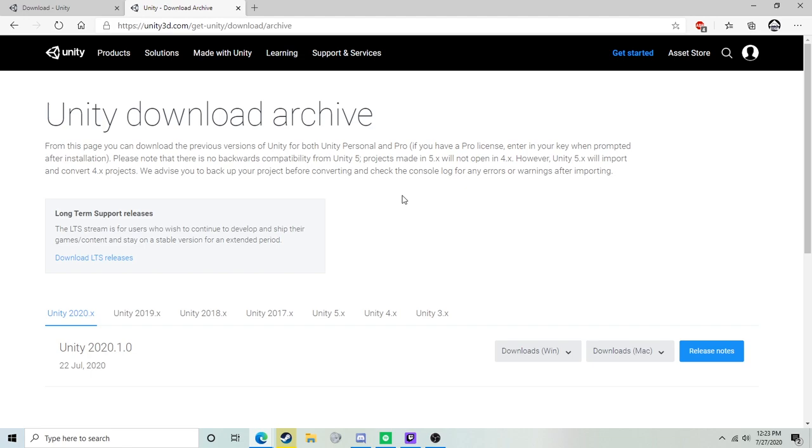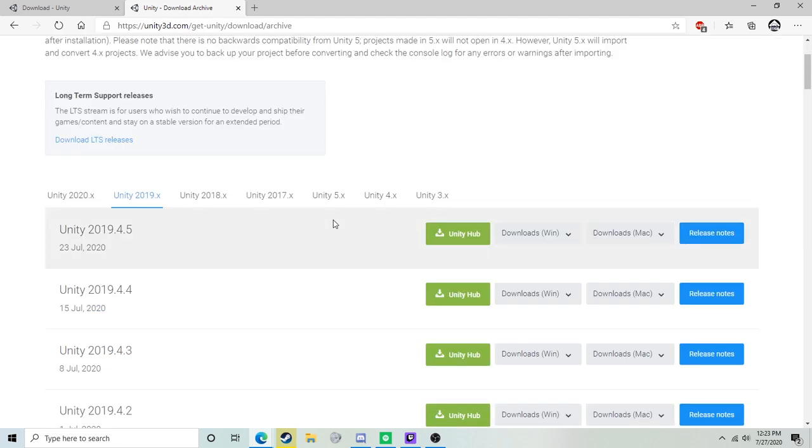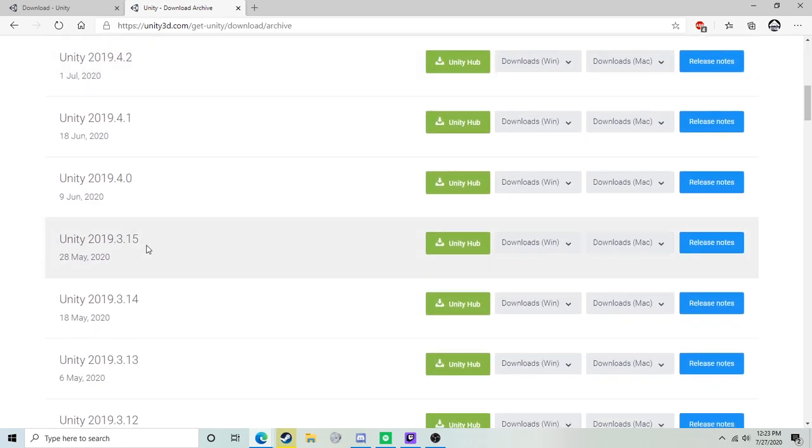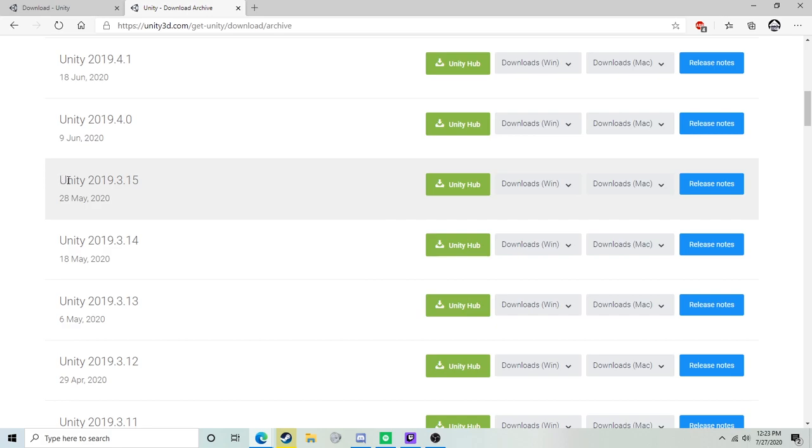Once Unity Hub has been installed, we're going to need to download a Unity version. In this case, we're going to be using Unity 2019.3.15. This is the recommended build as of the recording date of this video. If the recommended build changes, I'll make sure to adjust the description of the video. It is important that we use the correct Unity version. Once Unity Hub is installed, we can go ahead and click this button here, which will download this Unity version into our Unity Hub.